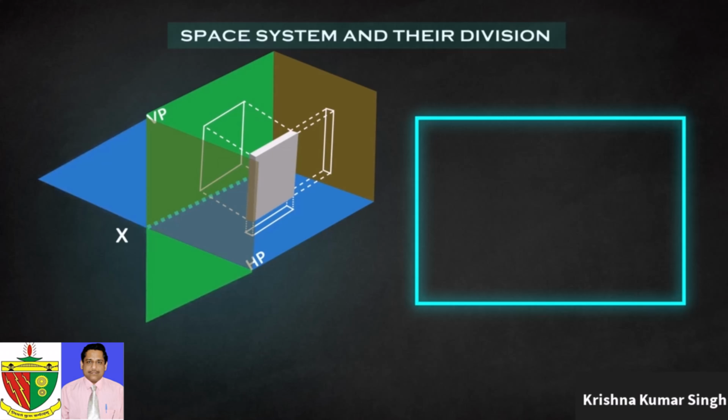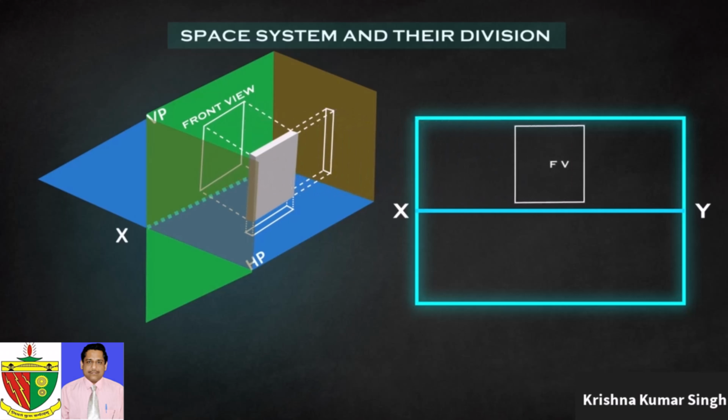For that, we draw a reference line, XY. The front view of the object is projected on the vertical plane. We directly draw it on drawing paper above the reference line. But the top view of the object is projected on the horizontal plane and it is perpendicular to the VP. So, we represent the top view of the object below the reference line.